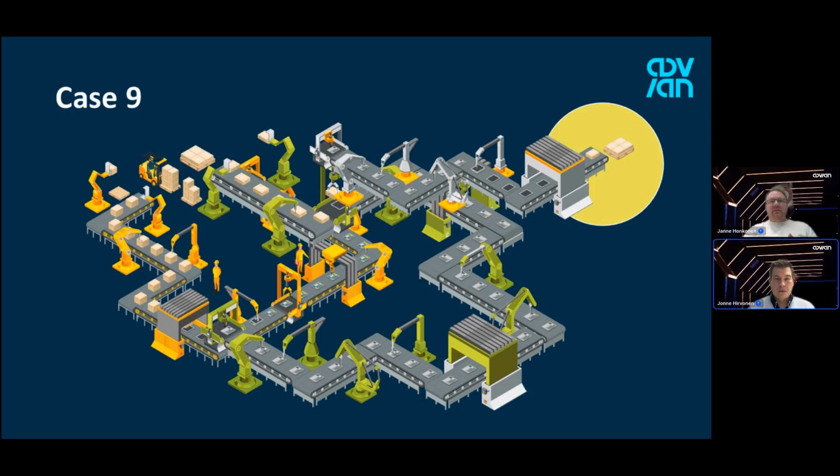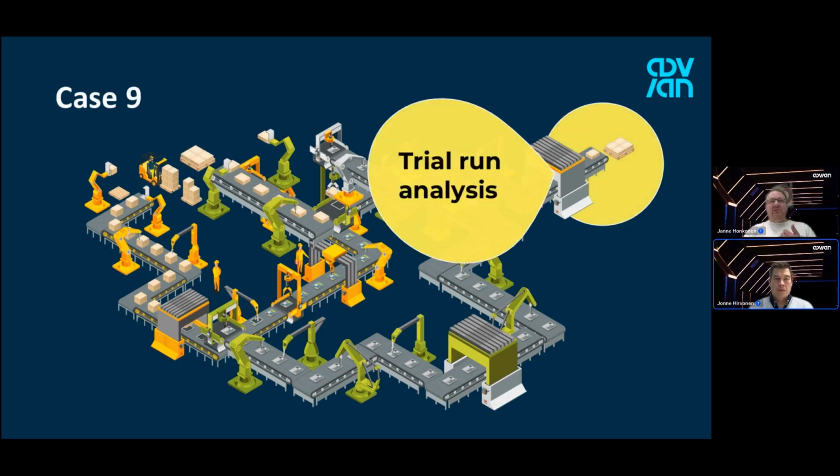One of the most important steps in production is testing the devices before they are delivered to customers. By utilizing a multi-sensor approach, we are able to reveal, for example, the reasons behind unwanted resonance. All this can be done in real time while the device is still attached to a tester. This gives an operator the opportunity to fix the issue immediately, not waiting for results until the next day. And during the trial run, we can also conduct another surface analysis to detect possible liquid leakages happening during the trial.